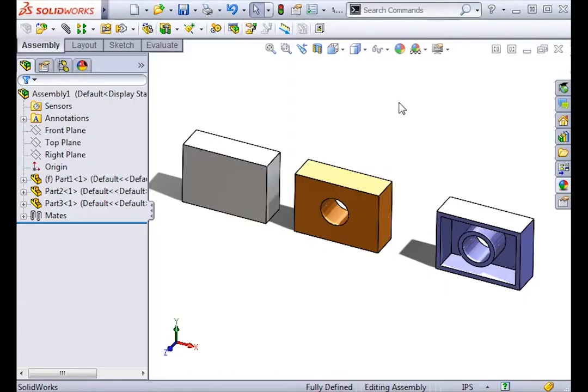Most users of SolidWorks quickly learn about the relationships between part, assembly, and drawing files. We all come to realize that assemblies and drawings have built-in pointers that allow these documents to find their relevant parts. If these built-in pointers are not sound, your assemblies and drawings are rendered useless. Simply put, to avoid file management problems, your task as a SolidWorks user is to make sure you preserve the integrity of the built-in pointers.